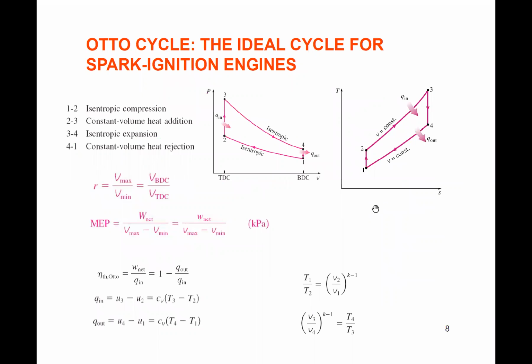All right, so chapter 9, we did our closed system. Chapter 9 is our gas power cycles, right? So this is a closed system one, which is the Otto cycle. The Otto cycle has isentropic compression, constant volume heat addition, then isentropic expansion, and then constant volume heat rejection. We described it with the compression ratio, so that told us about this change we have here.